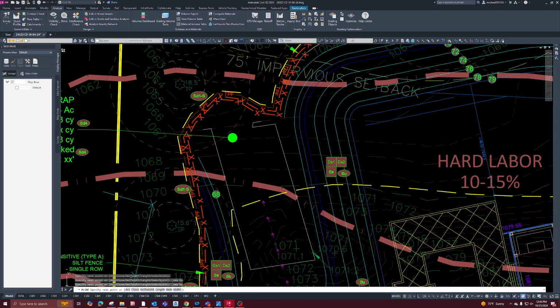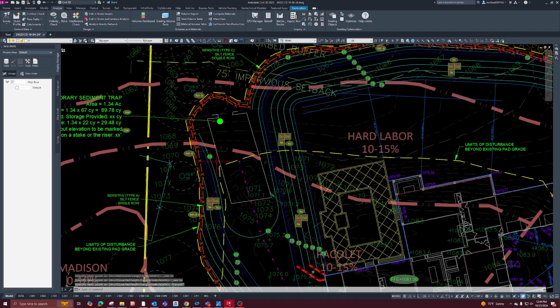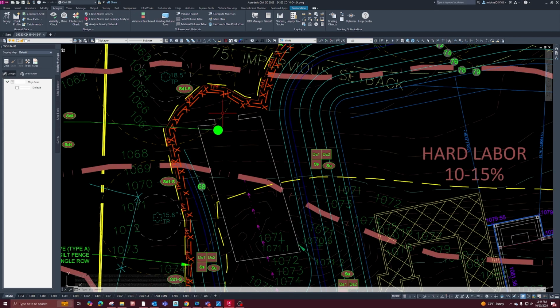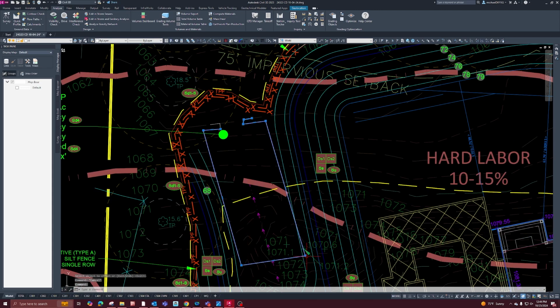I messed that up. So this is all higher than 66 on this side, and then it's lower here. So when it fills up, it's gonna spill out that way. Want to make sure if this is 68, make sure this is at least 4 feet away from there, so it's a 2-to-1 slope. Maximize our area we're using, and this is just kind of rough just to see if this is even going to be enough area for it. So we know we're far enough away from the 68. We'll delete that. We'll round it off some.